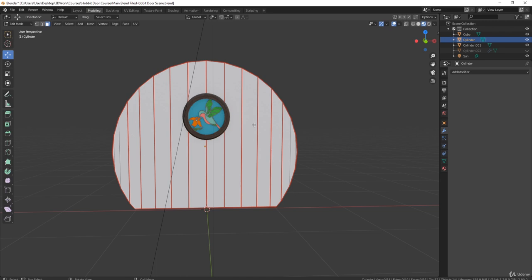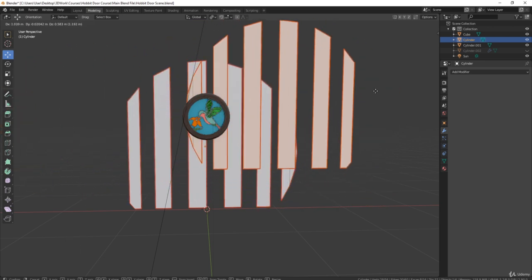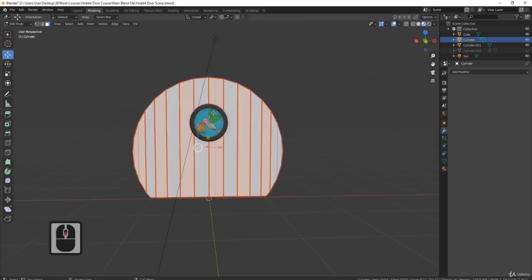All we need to do now is split these pieces of wood up. So I'm going to come to this side. I'm going to press L to grab this island, and I'm going to go to each one, just grabbing the island like so. And I'm going to press Y, G again, just to make sure that they're all split up. Right click and drop it back in place.